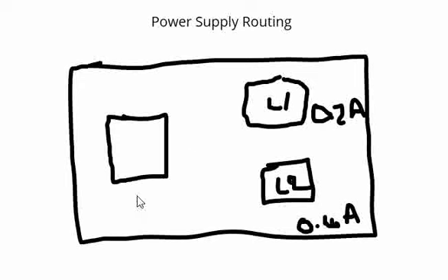Now, in this scenario, let us assume you have routed a signal initially like this because the LDO is closer to load 1, and from here we have routed the power trace like this, a thicker trace which can accommodate, let us assume, 1 amp of current. Now, what are the disadvantages of routing like this? This is almost a kind of daisy chaining, right?